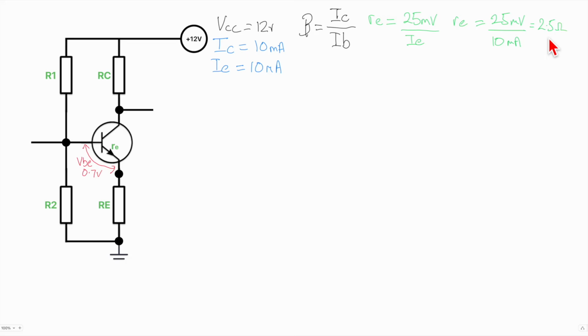So if I do a design here like I'm showing you, I want you to be able to go away, get these parts, put it together, and it to work in a similar fashion. The trouble is, if the only resistance we've got on the emitter is this little r e, we're at the mercy of the ambient temperature and everything else. So what can we do about this?